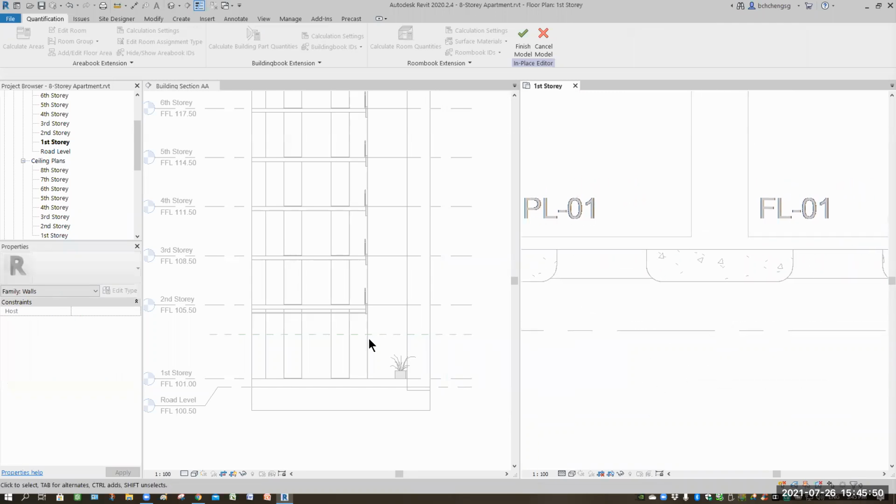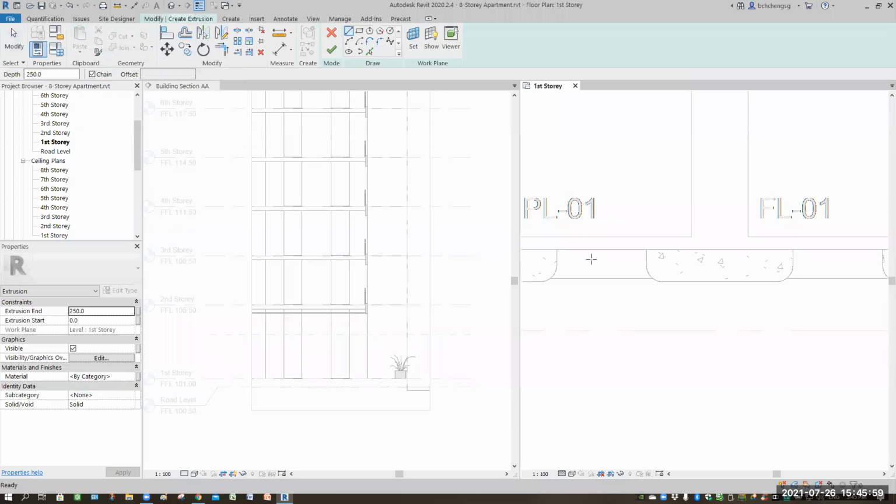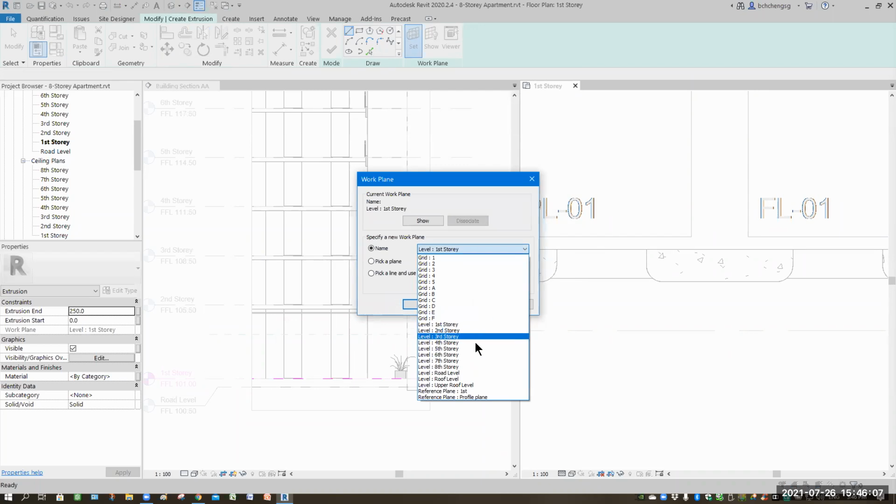Now, if you do these sketches, you want to stop at this level. Then you may want to create an extrusion. Before you do your sketches, set it where? There's something called first, right? Yeah, see? Here, reference plane first. Because normally when you sketch a reference plane, if you don't give a name, that means you only use and throw.